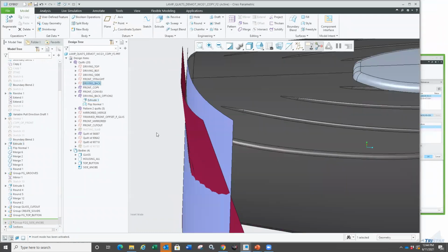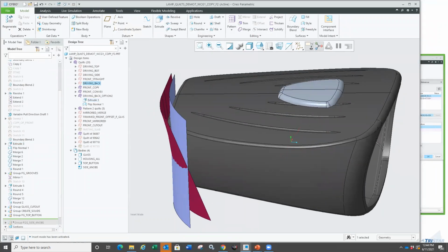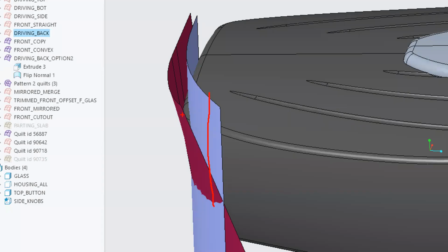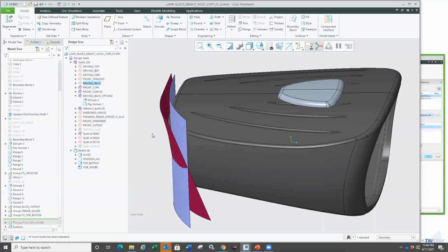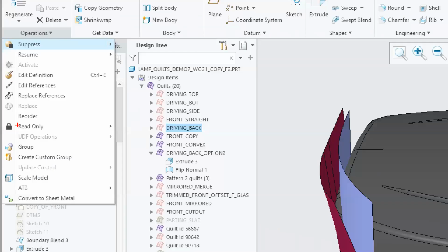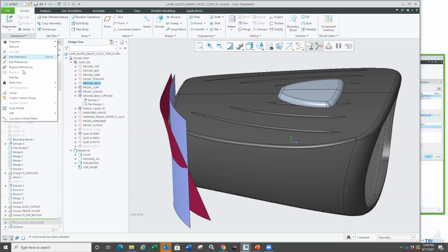So there it is, right? I'd like moving forward, the blue surface to be used instead of this, right? And all its children should update, or I might run into failure depending on what reference I give. For additional things, there's something that during my industry days I used to use on datum planes also, where you have a lot of parent-child relationships. It used to be in the old Creo Engineer days itself, right? Replace references, right there. So when I say I want to replace references, I have the option to select that.